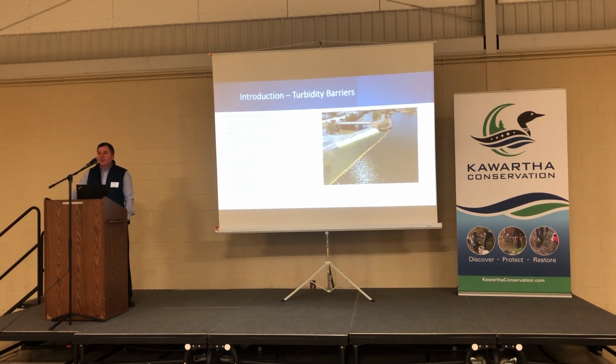Environmental regulations require that when silts are disrupted on site, they need to be contained. We find that most construction projects that are out for tender have a section which identifies the silt and sediment control and products such as turbidity barriers. Essentially, projects around or over a body of water with the potential of stirring up sediment require a silt curtain or turbidity barrier. Turbidity barriers, when correctly installed and selected, reduce the chance of an environmental spill.